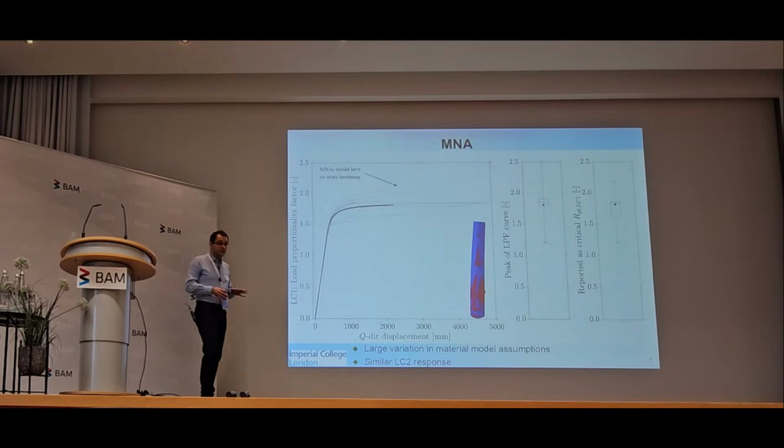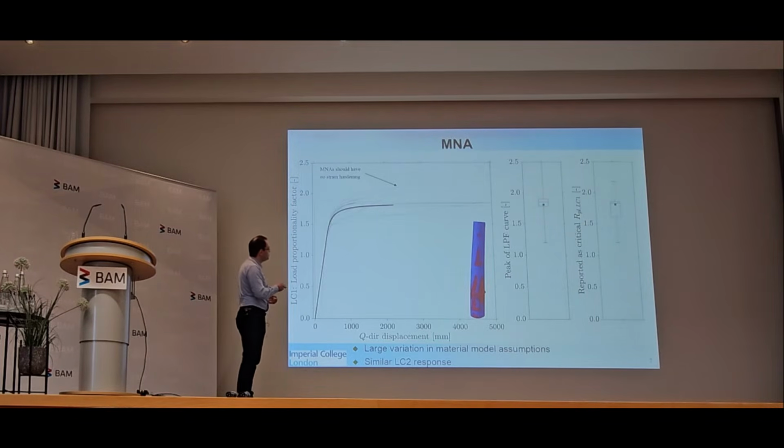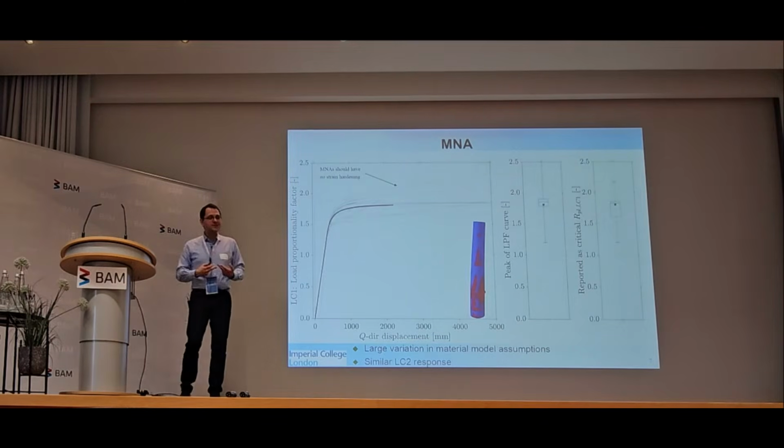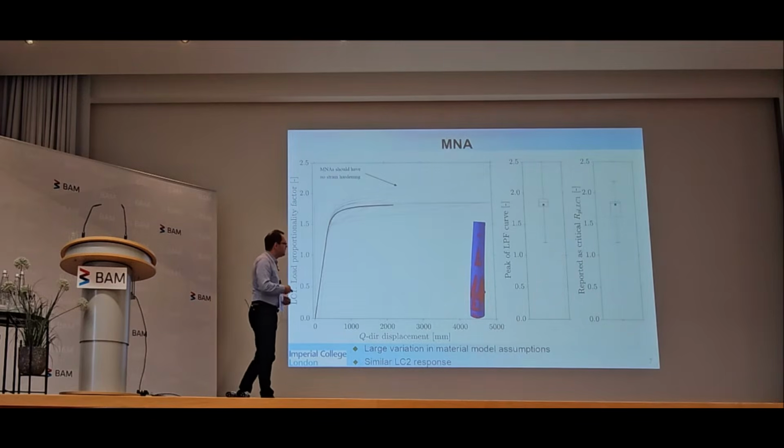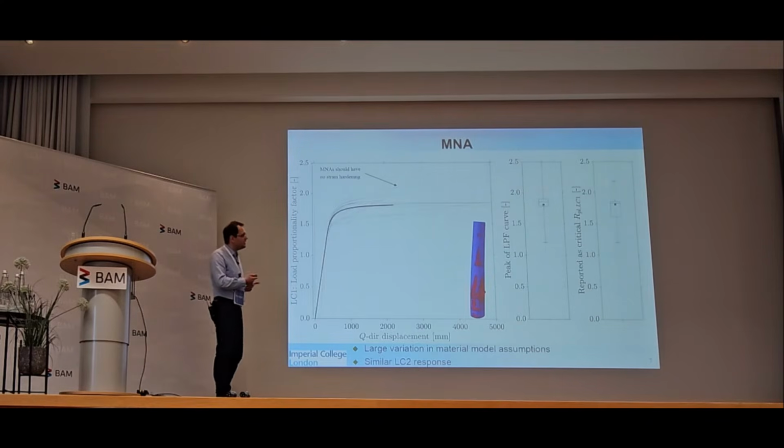That's completely fine. It has to report that much. You have to develop a full plastic collapse mechanism. You will get such high strains. That's nothing to be afraid of. This is an idealized reference limit state. So that's okay. There's no need to terminate it early. So I will show in a moment why both overestimating and underestimating are bad, but for different reasons. So this variability here is attributable to differing material assumptions, but also to differing termination criteria.